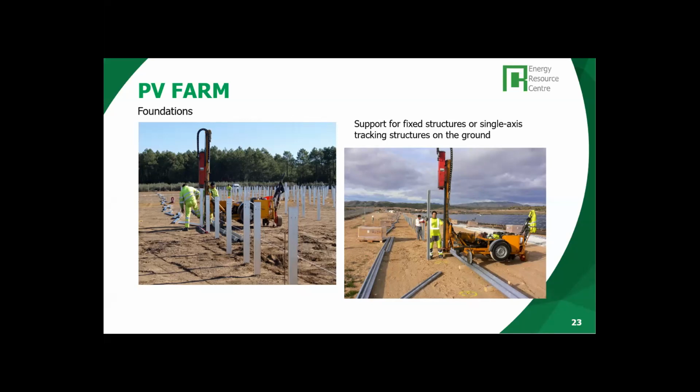I say driving because in Spanish it is "hincado". It is the first post you need to drive. It needs to be preceded by the geotechnical study and specifically the pull-out test in the site.